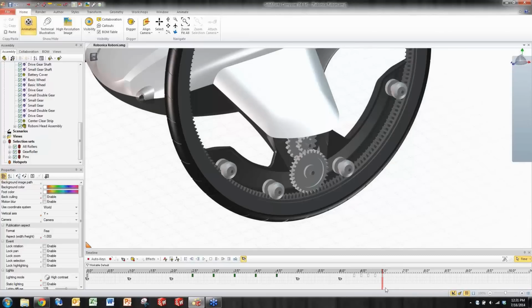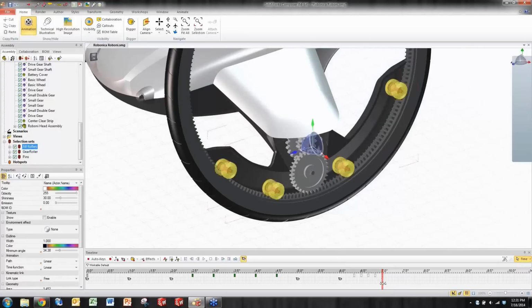So I'm going to grab these rollers again. I'm going to move my time bar a little further forward to maybe 7 3/4 seconds. And I want these things to disappear now. So they've flashed, they got the user's attention. Now I want these things to disappear. So I could come over here and highlight opacity and record it at 100%, move my time bar forward, change the opacity to 0, and then set a second key. That's the manual way of doing it.